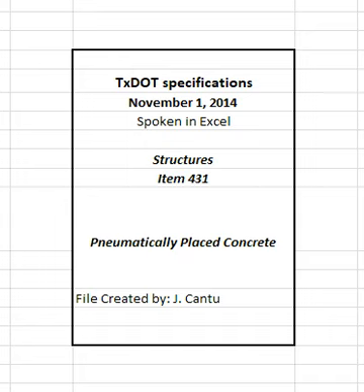Curing is not required for soil nail walls unless walls are the final exposed surfaces, in which case cure at least 4 days in accordance with Item 420, Concrete Substructures. Apply membrane curing in accordance with Section 420.2.7, Curing Materials, for tunnel and ditch linings and vertical or overhead patches as approved. 3.8 Repair of defects. Repair or replace debonded areas as directed.